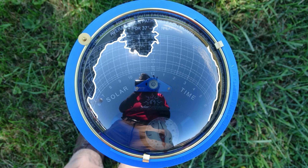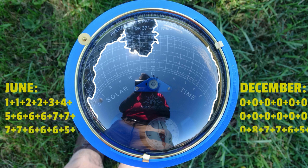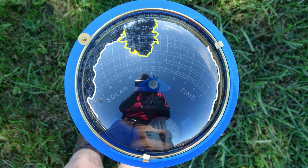You can process any of this information that you gather using various software packages, or you can assess the data manually. To find the percentage of radiation for each month, we'll add the small numbers in the unshaded part of each sun path arc. Once again, these small numbers indicate the percentage of the radiation that's potentially available during the specified half hour. In this example, the tree to the south is blocking between 14 and 38% of the radiation depending on the time of year. Hence, this location may only be exposed to about 62% of the radiation that's potentially available.